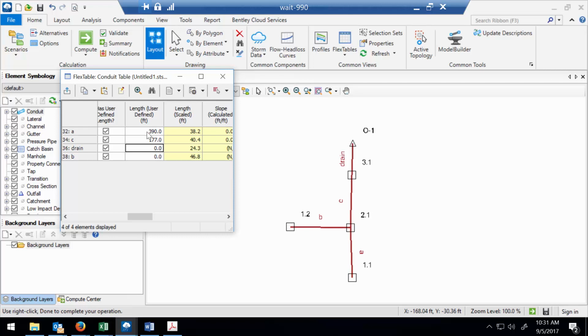And we just assume that downstream of this last junction is something that's going to be able to accept the flow that we give it. And so we want to make this last drain pipe really big and really steep so that it's not the limiting factor. So it's outside the scope, and its length doesn't really matter. I'll say 50 feet. Okay, and then pipe D.